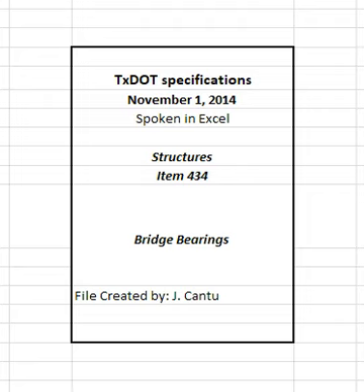At the fabricator's option, the steel top plate may serve the function of the sole plate between the supported structure and the HLMR bearing assembly provided it matches geometric bevel requirements, plan dimensions, and minimum thickness for the sole plate depicted on the plans, while maintaining the performance requirements and avoiding damage due to installation.